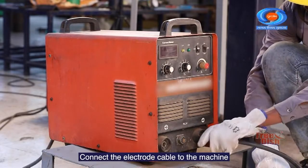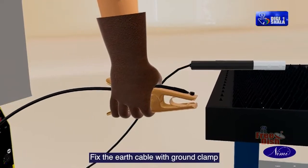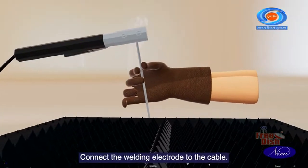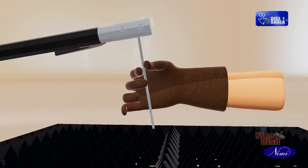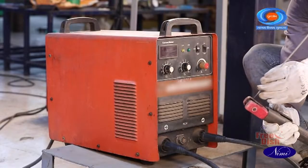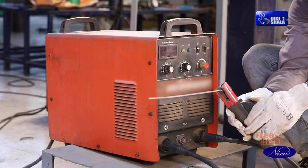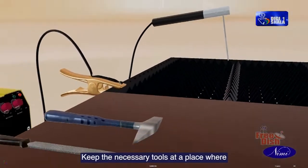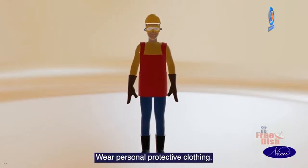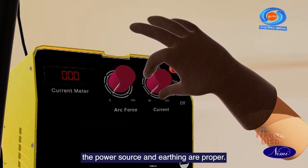Connect the electrode cable to the machine. Connect the earth cable to the machine. Fix the earth cable with ground clamp and clamp it to the welding table. Connect the welding electrode to the cable. Keep the necessary tools at a place where it should be easy to handle. Wear personal protective clothing. Turn on the arc machines and ensure the power source and earthing are proper.